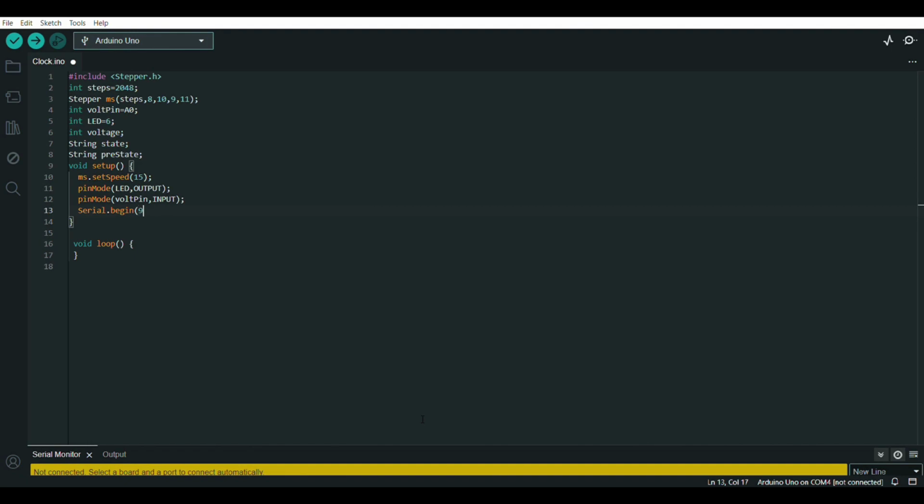You can use the serial monitor to keep track of different states. Now we need to use the method analogRead to read the value from pin A0. And we can print it to console in the next step.